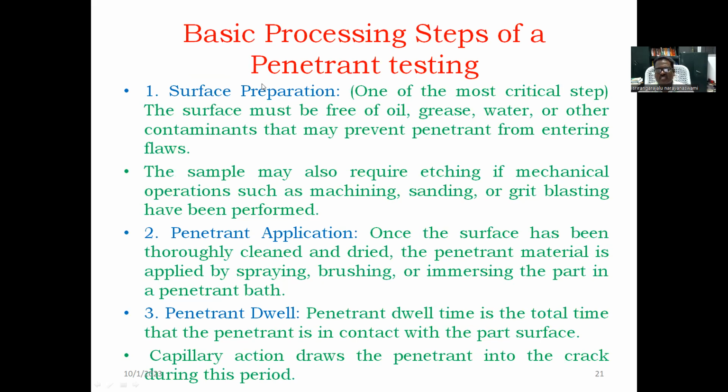So, the basic process steps of penetrant testing. Surface preparation is one of the most critical steps. The surface must be free of oil, grease, water, or other contaminants that may prevent the penetrant from entering flaws. The sample may also require etching if mechanical operations such as machining, sanding, or grit blasting have been performed.